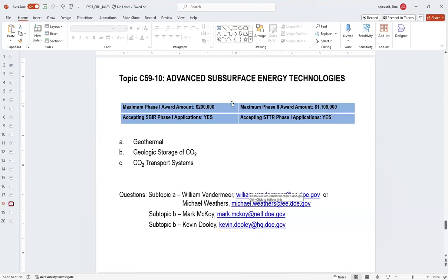Ultimately, this precipitation tends to plug up the reservoir, plug up pipes, redirect flow, and change the heat transfer rates. So it generally reduces process efficiency, and it's a problem that's pretty predominant across the geothermal industry, certainly at some geothermal fields more than others. But again, given the wide scope, we thought it would be a good topic area.